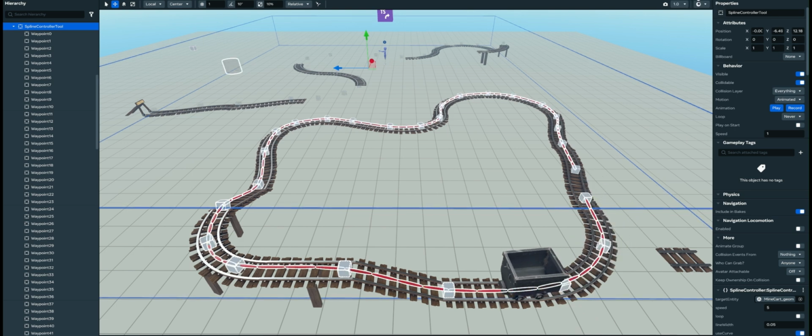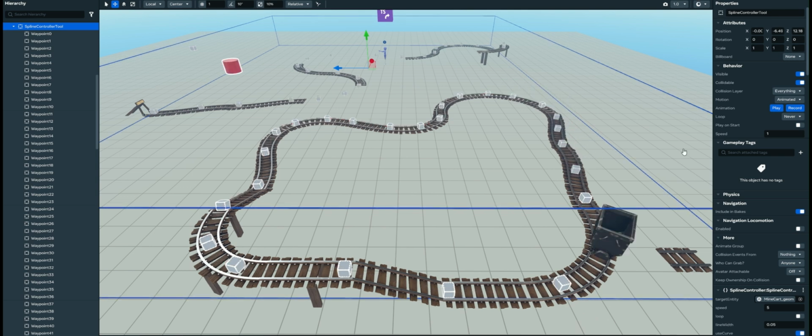You will notice that there is a first and last waypoint in this scenario. However, the track is continuous and this doesn't support good simulation logic. Therefore, under the speed input is a toggle to turn on loop, which will connect a path from the last waypoint back to the first waypoint to support continuous simulation logic for continuous track or rail systems.